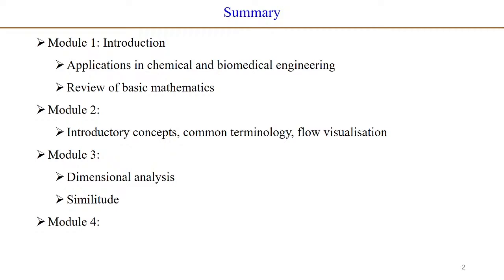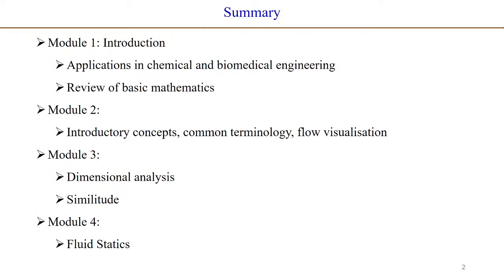Then in module 4, we looked at fluid statics, where we considered that if the fluid is stationary, what is the hydrostatic pressure? We all would have studied p equals rho g h. We discussed the Archimedes principle, how it can be derived from the hydrostatic pressure concept and so on.